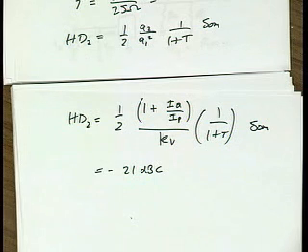Yes? So, by calculating the forward gain, instead of figuring out that Rm, could we just look at the expansion that we had done in the last part and see the coefficient of the linear term? No, because that doesn't include the loading. Now, in this case, the loading didn't affect the answer, right? But it could have. To keep the problem simple, I made it so that loading didn't really come into play. You have to assume that Rout is much lower than 60. That's also another assumption you have to make.